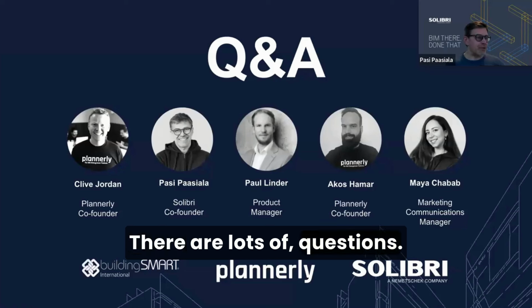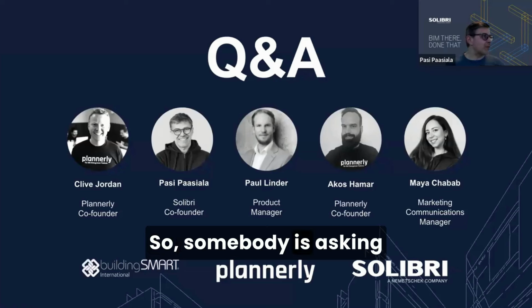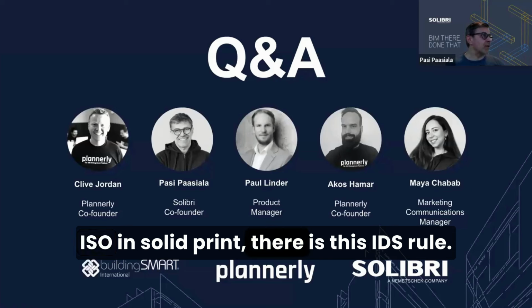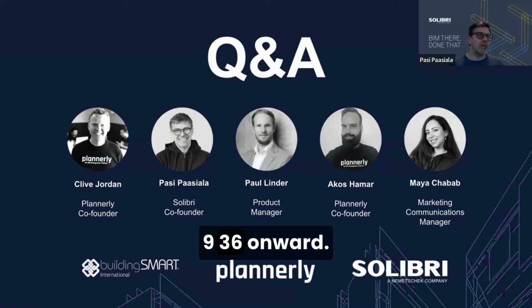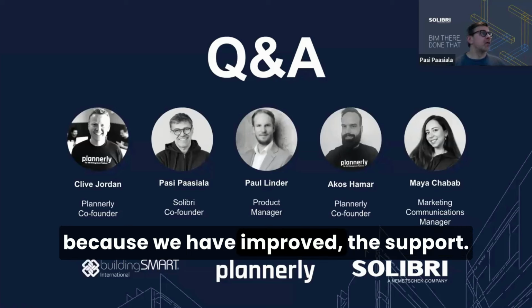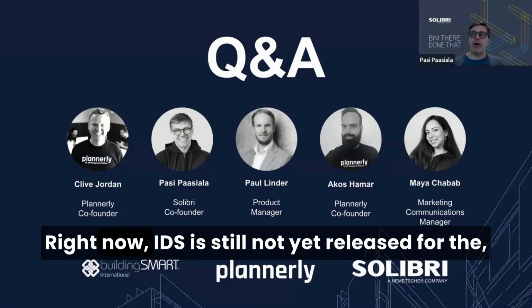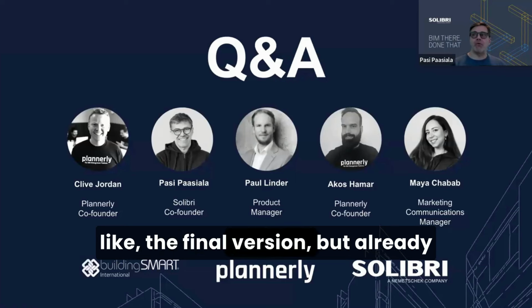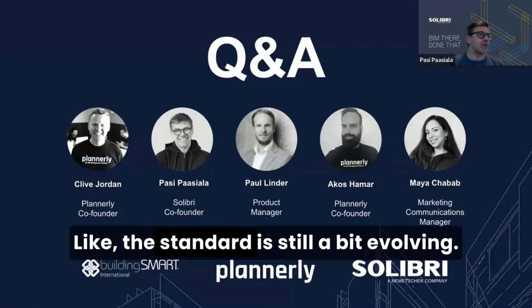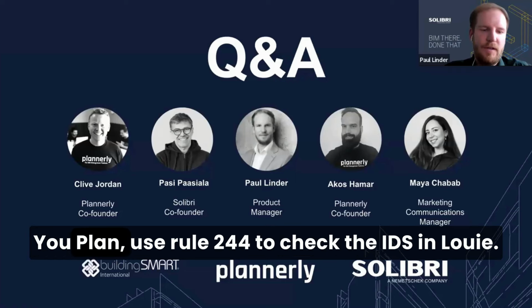Yeah, there are lots of questions. So somebody is asking, is there already rules for checking IDS? So in Solibri, there is this IDS rule 936 onward. I recommend to take the latest Solibri because we have improved the support. Right now, IDS is still not yet released for the final version, but already the version that is out is quite usable. The standard is still a bit evolving. You can use rule 244 to check the IDS in Solibri.